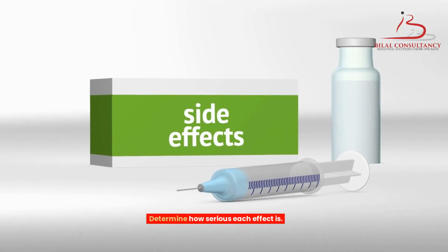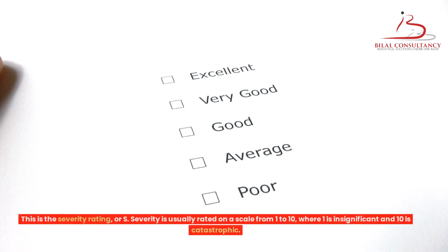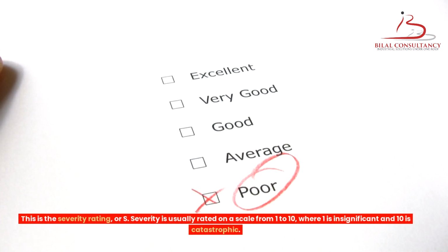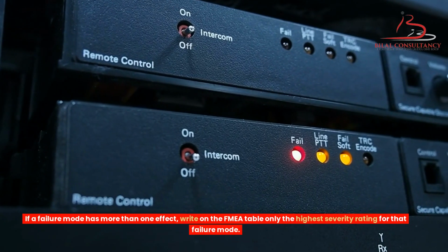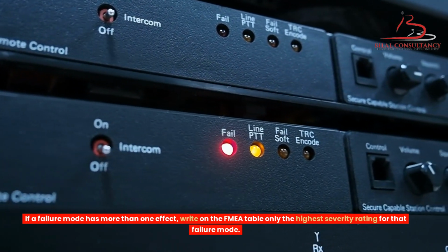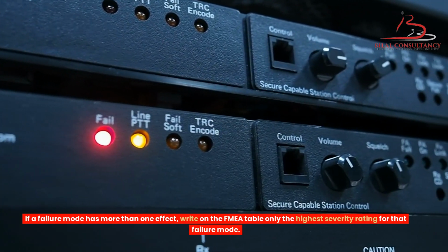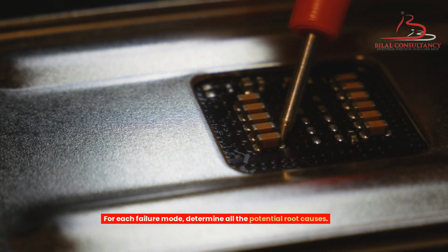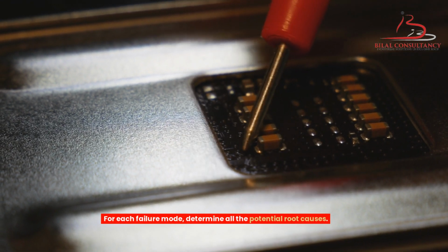Determine how serious each effect is. This is the severity rating, or S. Severity is usually rated on a scale from 1 to 10, where 1 is insignificant and 10 is catastrophic. If a failure mode has more than one effect, write on the FMEA table only the highest severity rating for that failure mode.